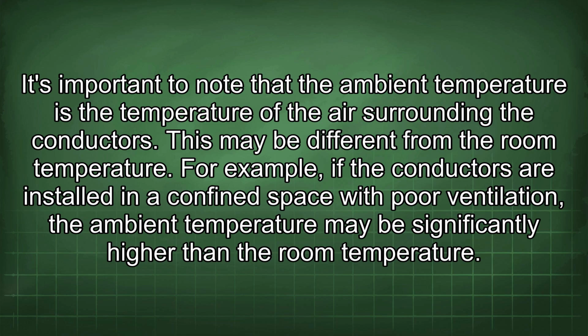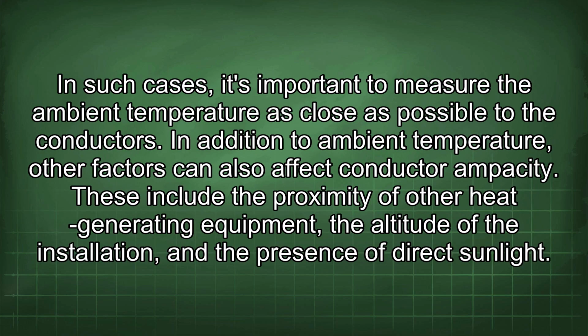This may be different from the room temperature. For example, if the conductors are installed in a confined space with poor ventilation, the ambient temperature may be significantly higher than the room temperature. In such cases, it's important to measure the ambient temperature as close as possible to the conductors.